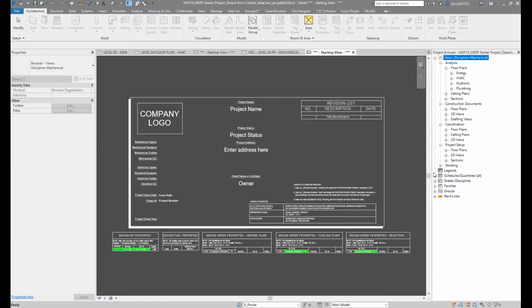And our shared parameter files are literally based upon the type of families we built and the parameters we built within our families. Our reasoning behind that is because we built a series of schedules as well, in order for us to be able to properly tie our family and our parameters into our schedules. So that's something that helps out tremendously, having a nice shared parameters file here and a nice setup with the MEP productivity pack starter model and modeling and everything along those lines.